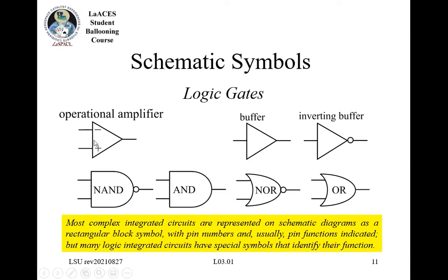The op amp, of course, is also important here because it is polarized with the signal input, it matters. It has a negative and a positive that you need to make sure you pay attention to. But whenever we install the device, you're going to see that these are typically full IC chips. So it's not like a capacitor or diode where it's going to have a plus and minus indicating this whenever we see it in the physical form.